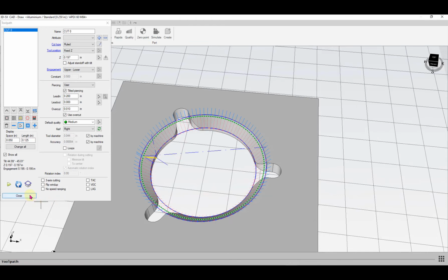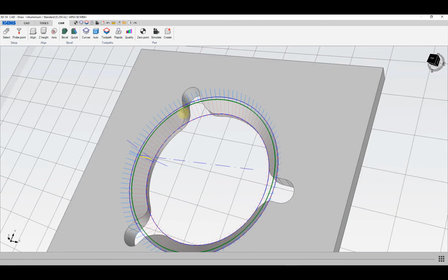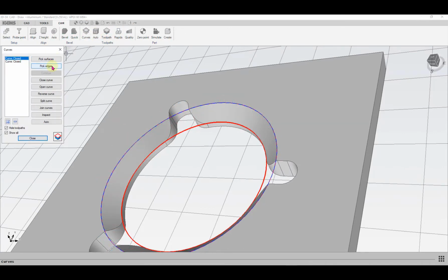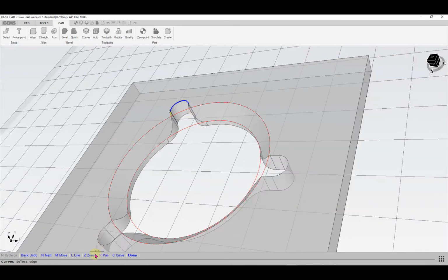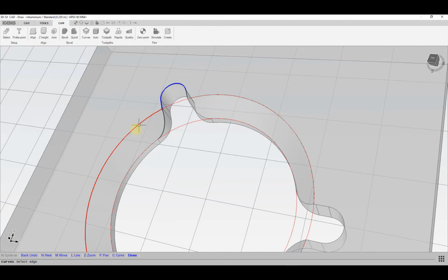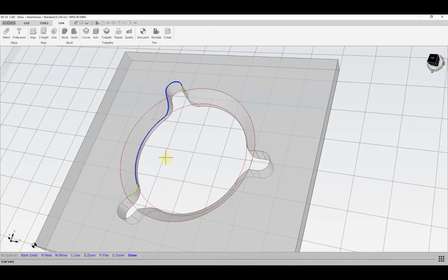And since we're here, we'll go ahead and program this vertical cut. This is kind of an interesting one where that cut is going down below the surface of the part. So we'll go to curves and we can pick edges. So sometimes on these more complex ones it's easier to do the pick edges option. So I can either just click on the next line, or down here at the bottom hit N on your keyboard, or just click on next and it'll find what it sees as the next little line segment in the model. And in this case here, it's seeing this one here. If you don't want to go in that direction, we actually want to go in this direction. I can click on that line to send it in the right direction.